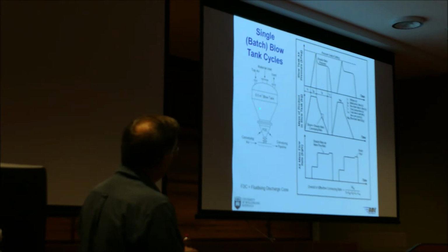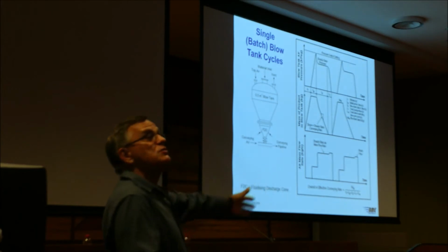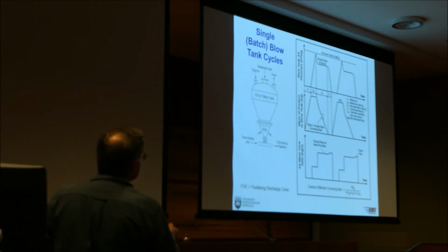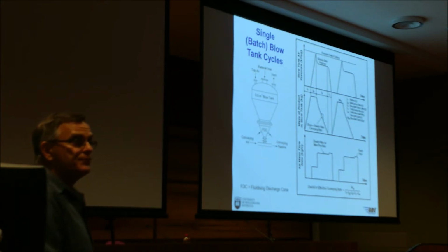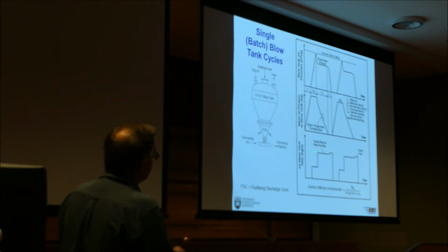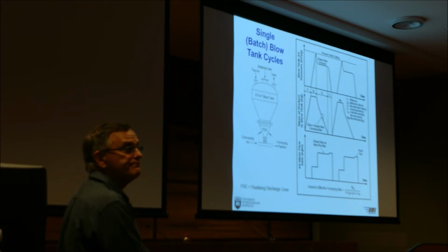Now we have a set point. So once we reach our set point, it could be 200 kilopascal gauge, which is that point there. We say we're ready for discharge. At that point, we turn the conveying air on, then you see the air jump up. This is the total airflow going through the system, through the pipeline. Right, and then we open the outlet valve at that point.